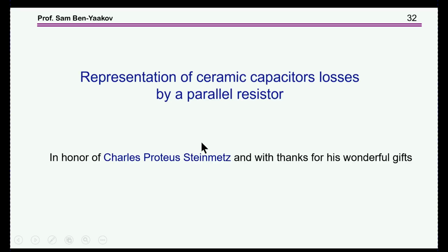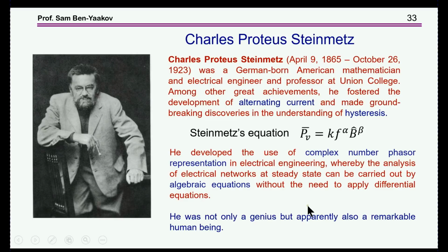Now, I did some work on the question of how to model the losses of a ceramic capacitor. And as I've said, the classical, conventional approach is to put the ESR in series. And as it turns out, theoretically it's incorrect.